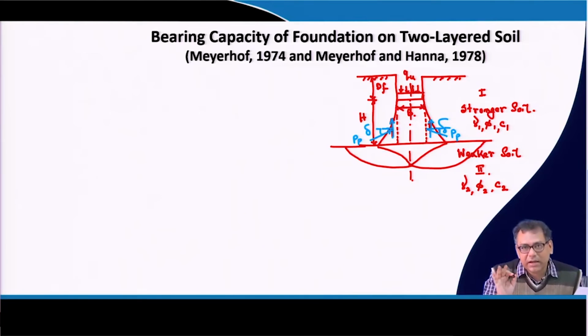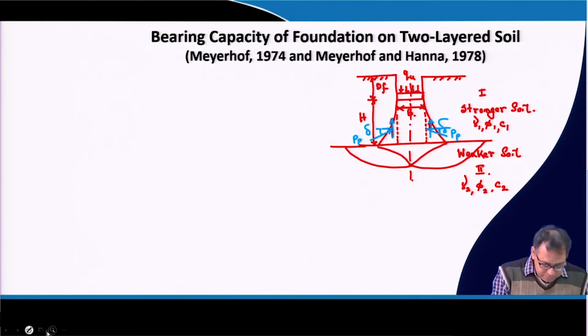So, what is delta? Delta is the friction angle between the soil and any other object. Okay, but here this angle is basically along that dotted line. So, it is soil versus soil, because later on I will modify that, and now it is considered as a delta.